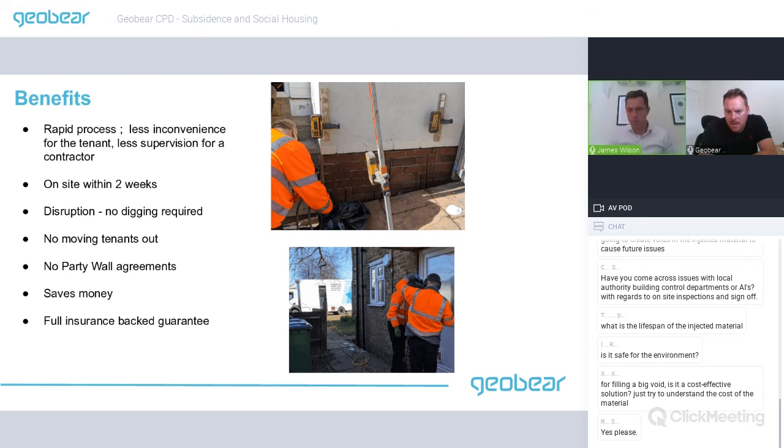Do you treat dampness from the ground, asks Hannah. It would depend. The material is totally waterproof, so water cannot pass through our resin. So it's often used to seal tunnel linings. You can inject behind things like sheet piling to seal that. But it's difficult to provide a total waterproof area. I'm not exactly sure what Hannah means by treat dampness in the ground.